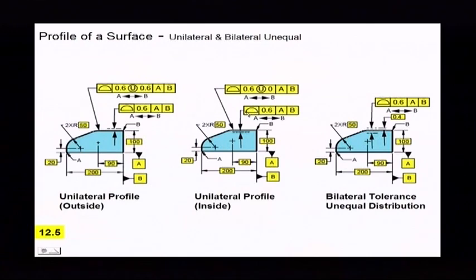Now we can still use the earlier method. You see this? This is still available. You can still use that for your drawings. What the new symbol and the old one are really telling you, kind of on the side, is that this is going to be phased out, probably by the next standard. Can't tell you that for sure, but probably that's where it's going to go. The reason we use that symbol is that if you're tolerancing solid models, like we showed you earlier, it's very difficult to come in and point and try to show a line on the inside. And that symbology, that circle U, really came from the ASME Y14.41 standard, and we just dragged it over and used it in the ASME Y14.5 2009 standard.